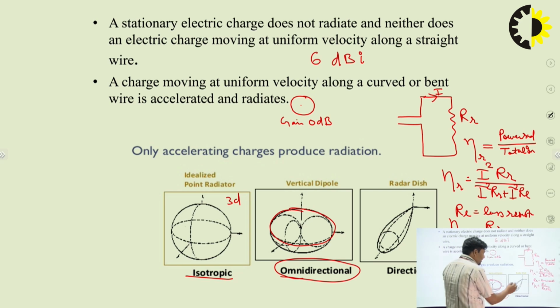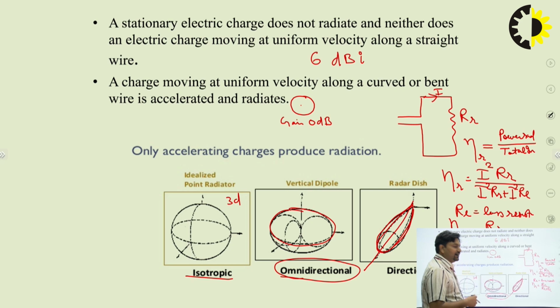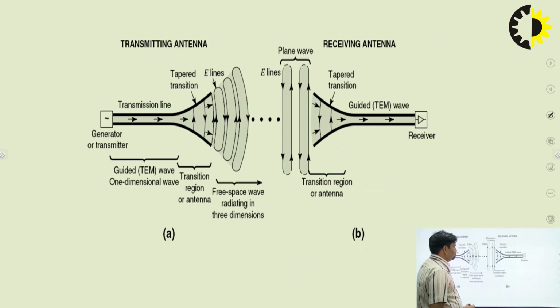And for the directional antenna, you just see the radiation pattern. What is the radiation pattern? This is the intensity of the power radiated by the antenna in a particular path. We can see that it is directional in nature: in this direction it is maximum and in other directions it does not appear. So we can say this is a directional antenna. By using the radiation pattern, we see that this type of antenna is designed. This one is isotropic, omnidirectional, and the directional one.